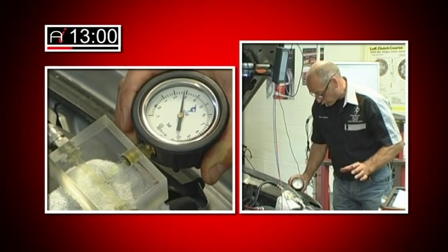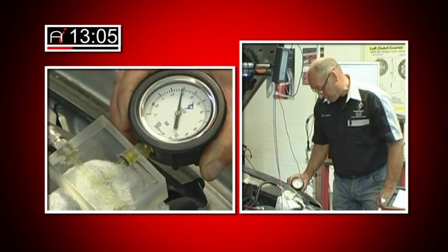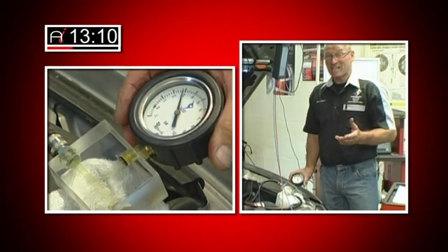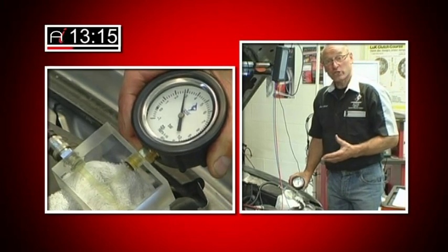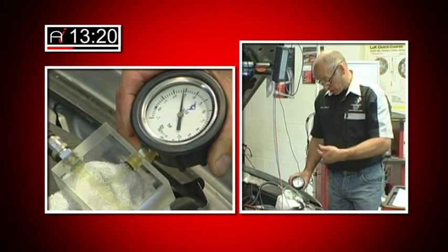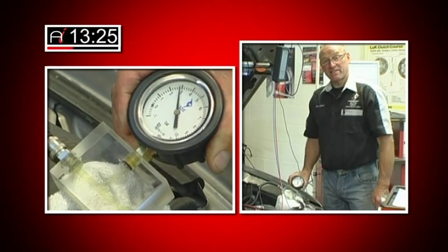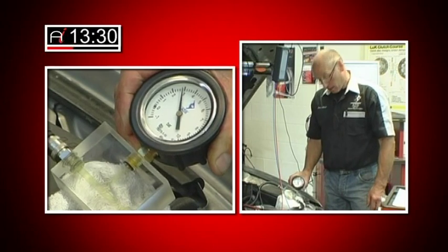So we've got 2.6, 2.8, 3 bar of pressure. It's holding good. Now, of course, with intermittent faults, at any time the pump could cut out. There could be an issue with this hydraulic pressure. At the moment, there isn't. The pressure came up promptly. It's holding steady. There is no cavitation whatsoever within that sight block. And I have to say, at the moment, I have no problems with that.